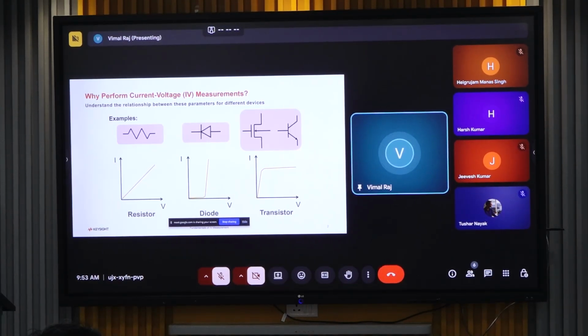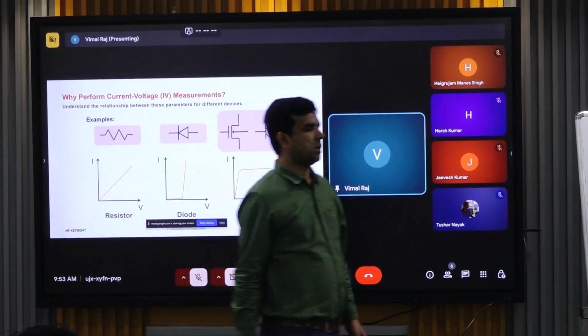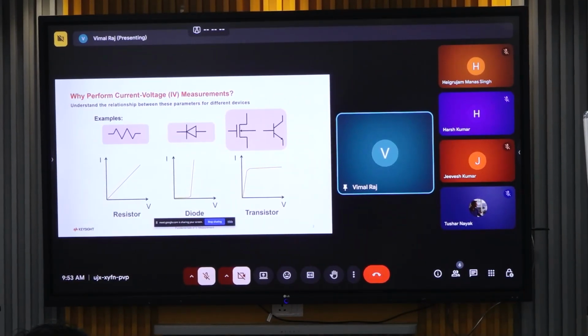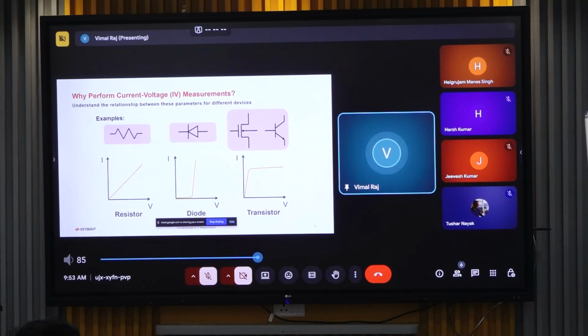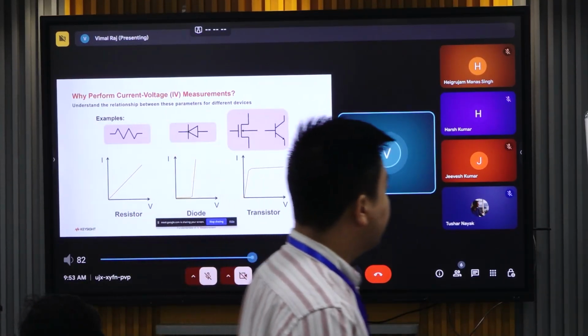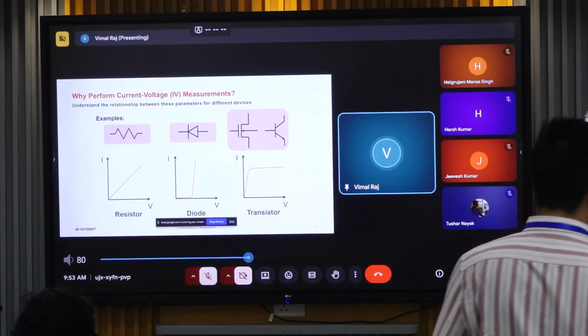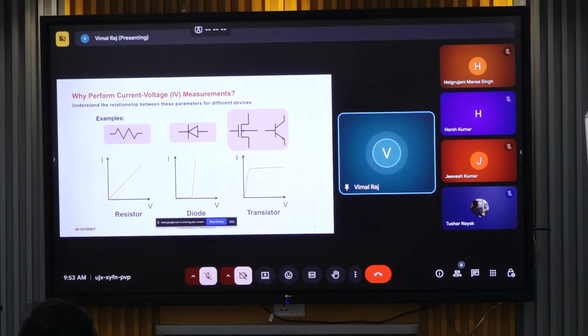If you want to see accurate characteristics, it is more important how many steps we are splitting the sample into. That also is important. If you use only 10 samples, we can't get the exact curve. If it is linear, we can get it, but if it is a non-linear curve, we can't get the turn-on voltage or turn-on condition. What will be the maximum peak? We can't see the time frame and all of those things. If we want good characteristics, we need to prepare more samples.